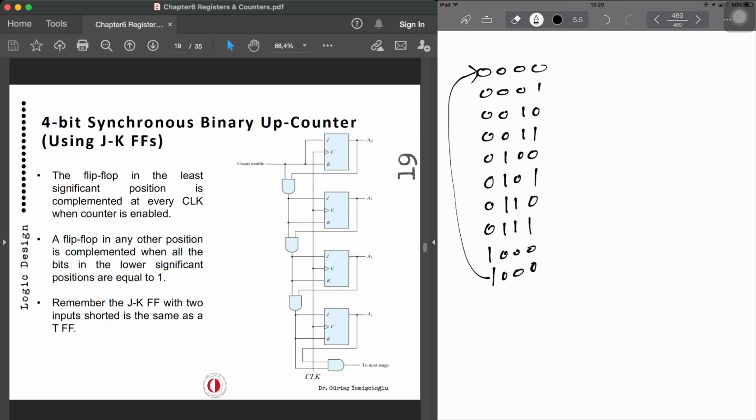They're not coming from outputs. And these outputs are fed in with the count enable so that they can trigger each other and count from 0000 up to 1111, for example. Okay, this is not BCD, this is just an up counter. So as this is 4-bit, it starts from 0000, it can go up to 1111. And the clock is all on the rising edge.